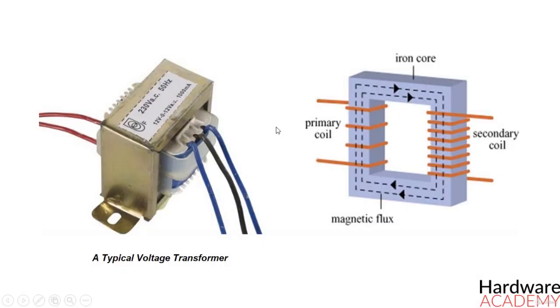A transformer is a device consisting of two closely coupled coils called primary and secondary. An AC voltage applied to the primary appears across the secondary with a voltage multiplication proportional to the turns ratio of the transformer and with a current multiplication inversely proportional to the turns ratio. Usually transformers are quite efficient. The output power is very nearly equal to the input power, and therefore a step-up transformer gives higher voltage at lower current.